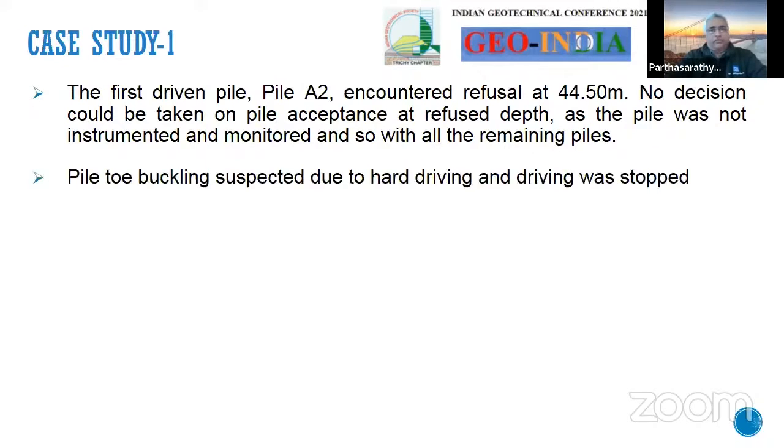Pile toe buckling was suspected due to hard driving because the blow counts were extremely high, and thus the driving was stopped. There was no plan for remedial measures because it was not at all indicated in the geotechnical investigation. So the entire team was demobilized. I'm sure a lot of people lost a lot of money on this project.